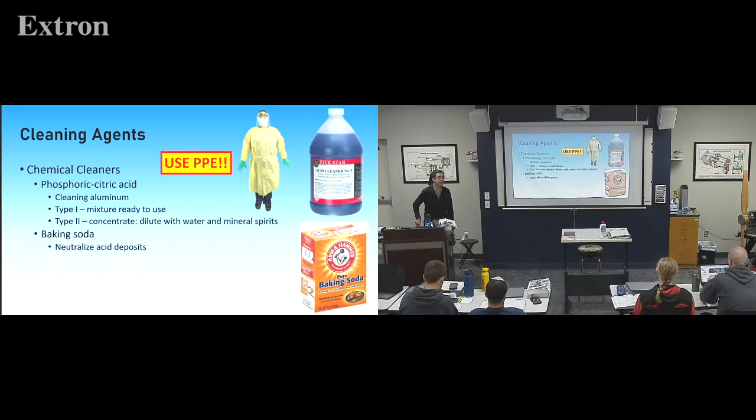And with acidic things, make sure you have some baking soda nearby. If you splash it on yourself, wash it off, wash it with some baking soda to help neutralize that acid. So baking soda neutralizes acid, what if you have, let's say, a NiCad battery? Correct. You need something acidic. So, if you are working with NiCad batteries that are not sealed, keep lemon juice handy for your skin to wash it off, or your eyes, to help neutralize that.